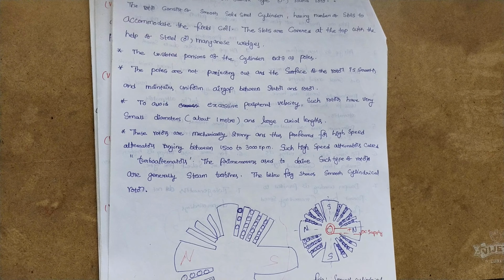Now assume that E1 is the EMF induced in one slot, and E2 is the EMF induced in another slot. Conductor 1 and conductor 2 are there. Two conductors, or two slots, make one coil. E1 is the EMF induced in one conductor, and E2 is the EMF induced in another conductor. The phase difference contributed by each slot is the slot angle beta, equal to 180 by pole pitch, 180 by 9, which equals 20 degrees. For EMFs induced in conductors placed in adjacent slots, there will be a phase difference of beta degrees between them.